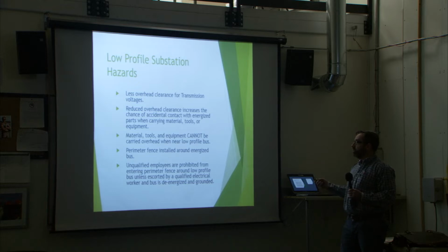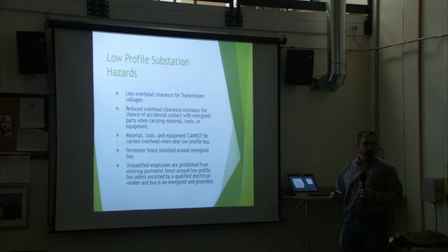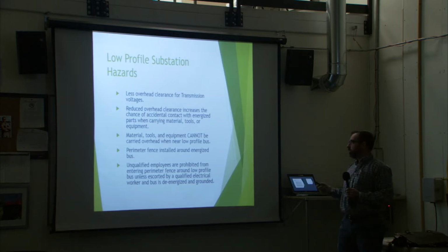Obviously there's less overhead clearance from your transmission voltages. So this reduced overhead clearance increases the chance of accidental contact with energized parts when carrying materials, tools or equipment. So with that being said, you cannot carry anything, tools, material, equipment, overhead when you are near a low profile bus.